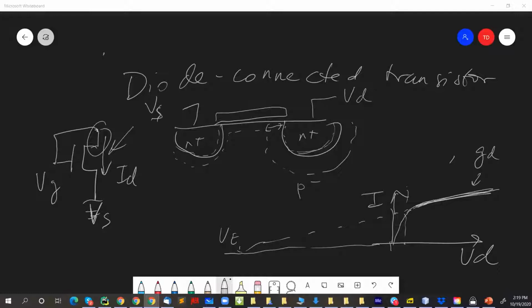Anyway, sorry to interrupt. That's the whole channel length modulation stuff. So basically, if you want a flat curve, make a long transistor. Simple. Okay.